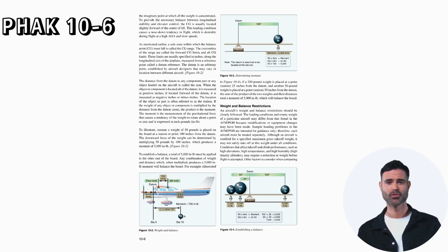Weight and balance restrictions. An aircraft's weight and balance restrictions should be closely followed. The loading conditions and empty weight of a particular aircraft may differ from that found in the AFM/POH because modifications or equipment changes may have been made. Sample loading problems in the AFM/POH are intended for guidance only. Therefore, each aircraft must be treated separately.